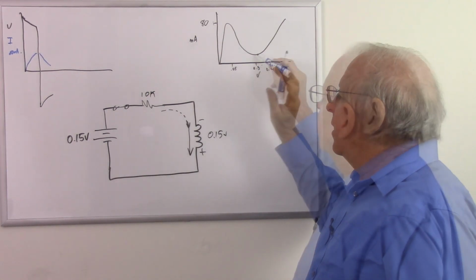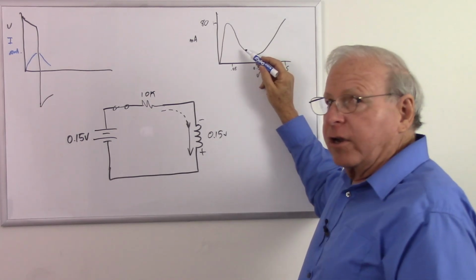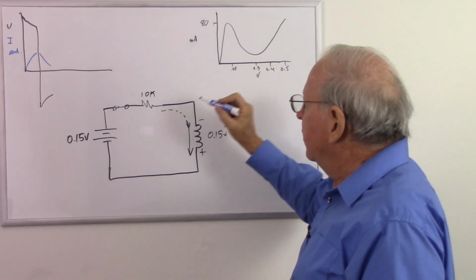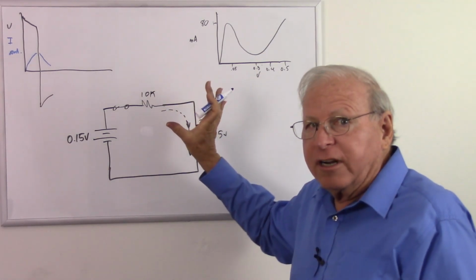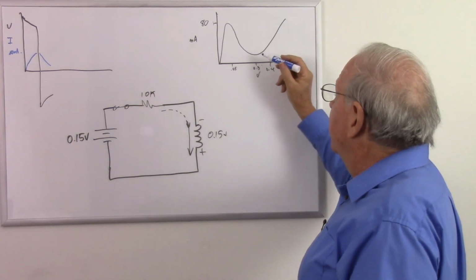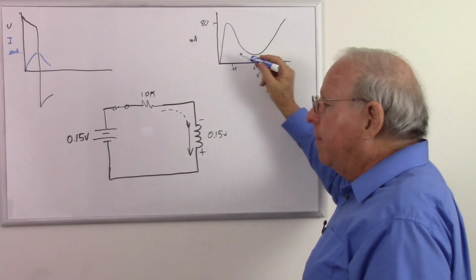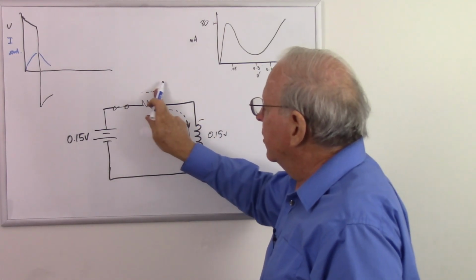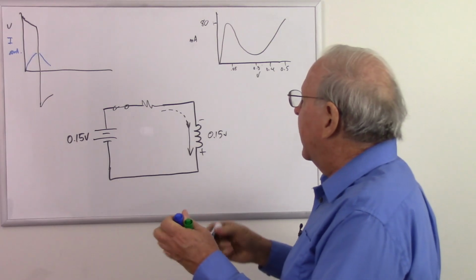And so the tunnel diode is supposed to allow the current to go up, but the inductor is not going to allow that current to change. So the tunnel diode is going to start decreasing its resistance, trying to allow the current to go up as the voltage goes down. The inductor is not going to allow that, so this is going to suddenly drop to a very low resistance. Let's put it back at 6 ohms.